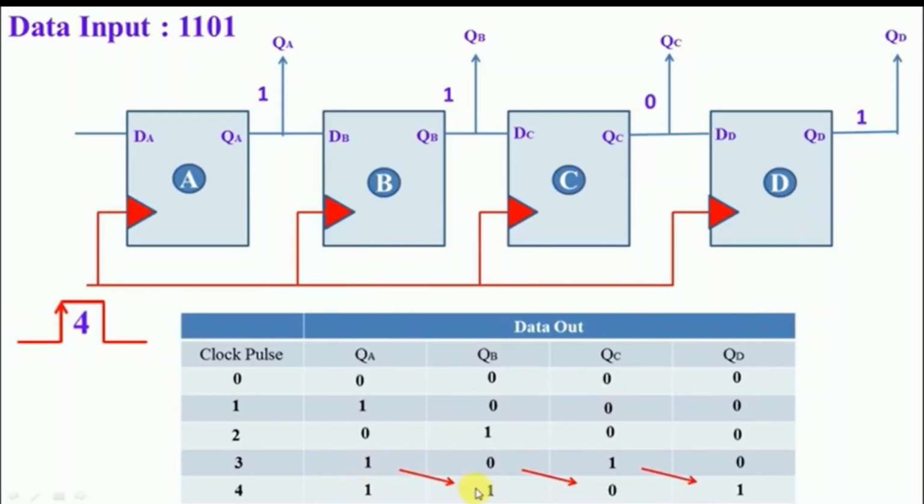So an excellent example of the sequence of operation that's necessary to shift from left to right in a serial register, and we can see the 4 individual clock pulses that are necessary in order for all of those bits to be set.